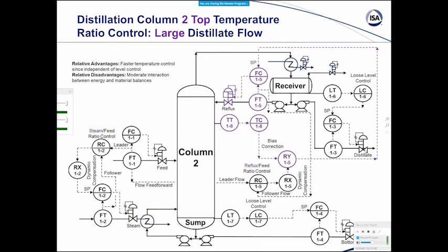So you want what you might call maximum absorption of variability in terms of level. I call it minimum transfer of level changes to the manipulated flow. And you can do that through some intelligent tuning, which we've covered in other WebExes. So you want loose level control.